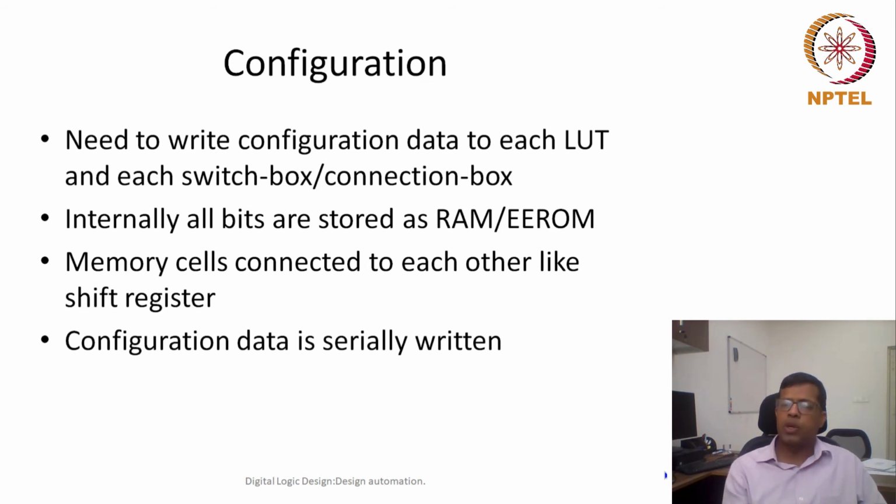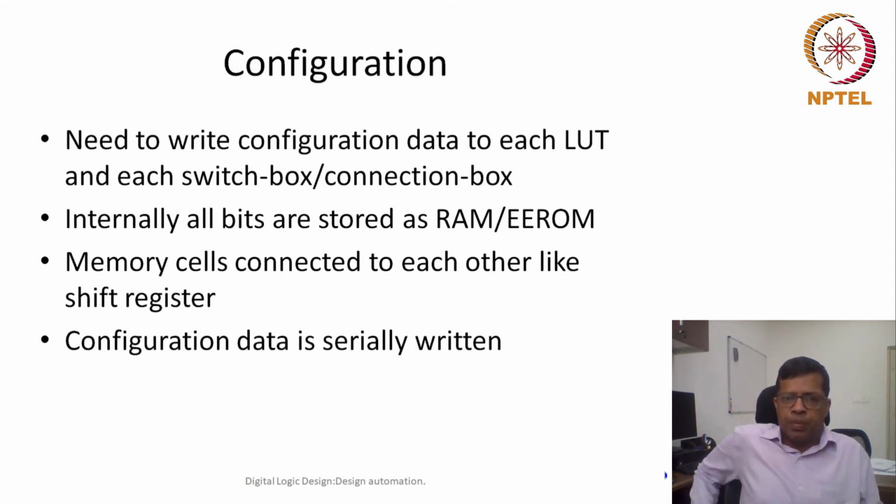People also use EEPROM, so that if at all need arises, it could be reprogrammed in some other way. Usually in the lab, whatever FPGAs we are using have all the configuration data stored as RAM, not ROM, so that we can reprogram every time we power up.